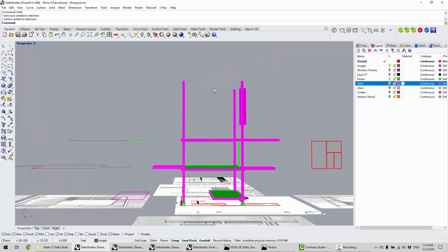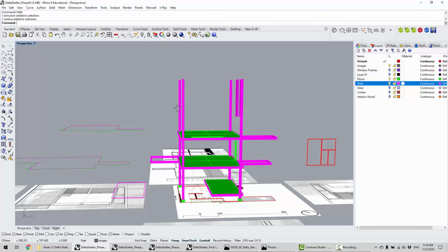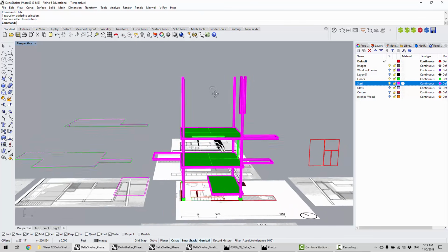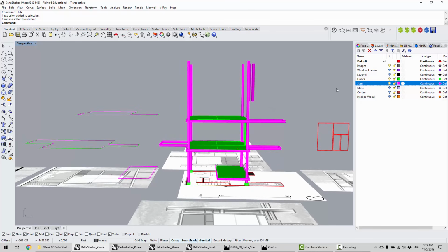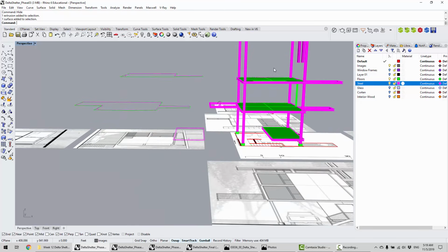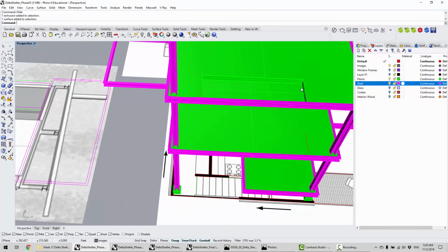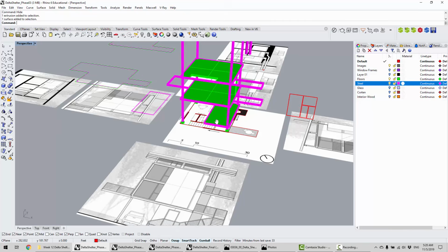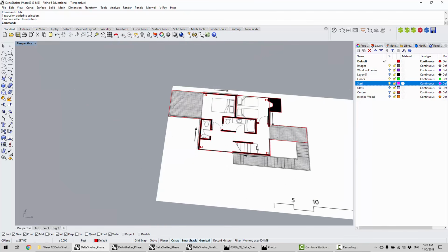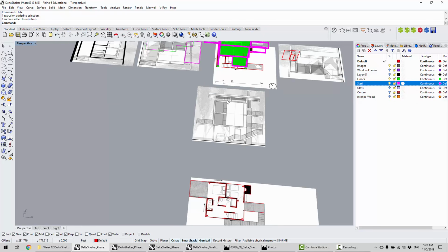And you'll see I just extruded it tall enough to punch through the roof. We'll trim it later, right? So I'm not worried about how it fits under the roof. Just overshoot it, right? Okay, so once you have that, don't forget that there is this opening for the stair that goes down this way. So this is the beginning of the stair, that's the end of the stair going up, right? So you'll have to get some of that information from between the 2 floor plans, that one and this one, to match it up, right?